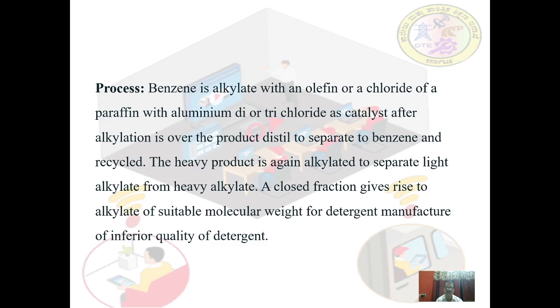The heavy product is again distilled to separate light alkylate and heavy alkylate. A closed fraction gives rise to alkylate of suitable molecular weight for detergent manufacture.